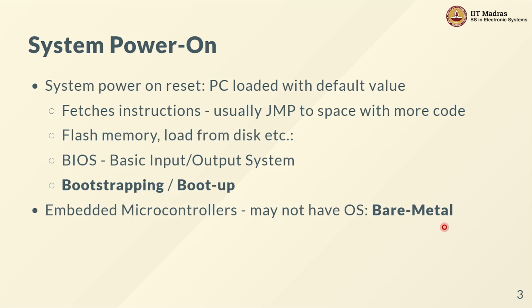The program that I want is directly aware of everything that the processor can see. Every connection, every peripheral is known to the program, and the program has to then decide how to interact with it. If you want a timer, the program needs to go and set values in the registers and so on. So this is sort of the default mode in which systems operate, right? You have a processor, you have a motherboard, you have some program in memory. That's called bare metal operation.